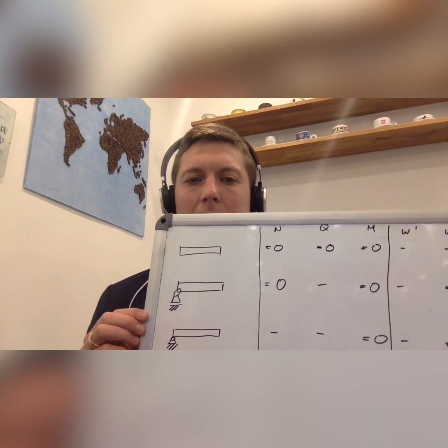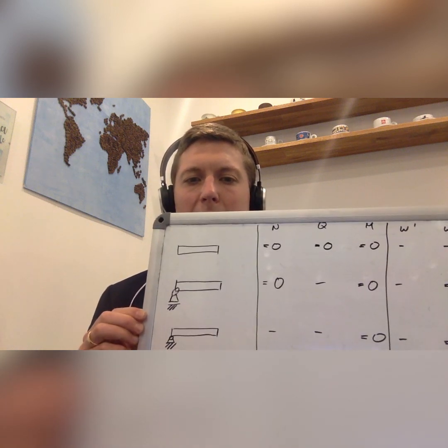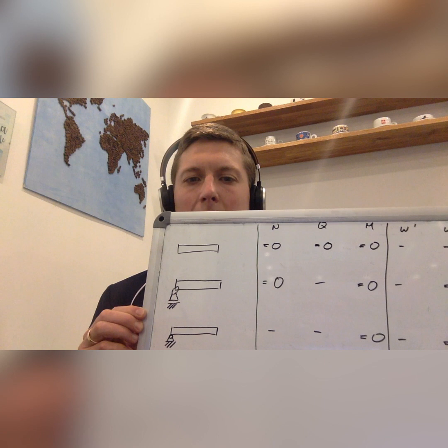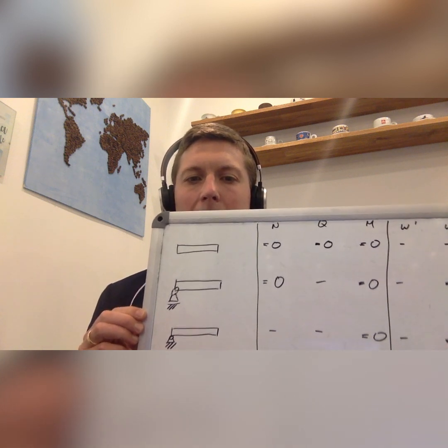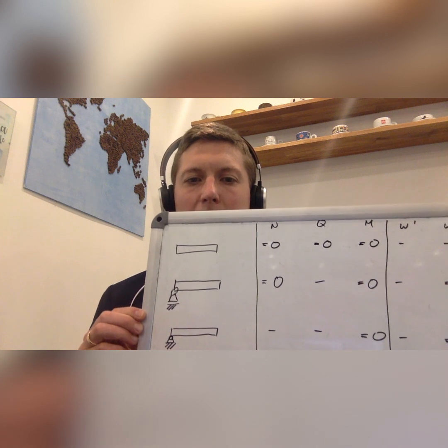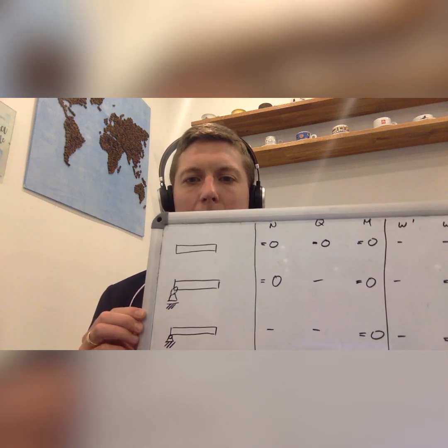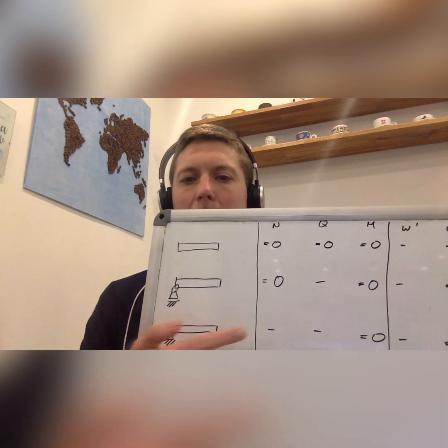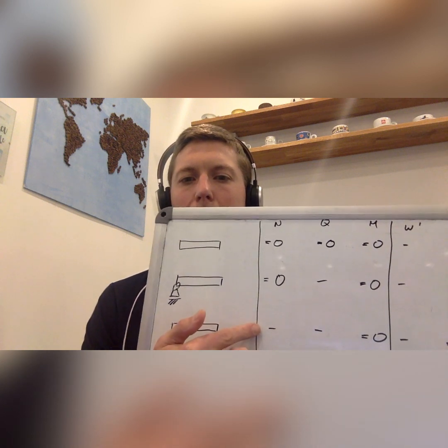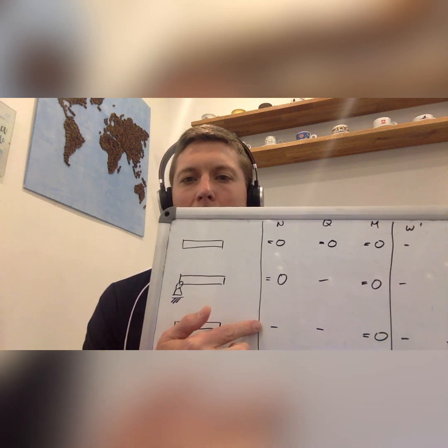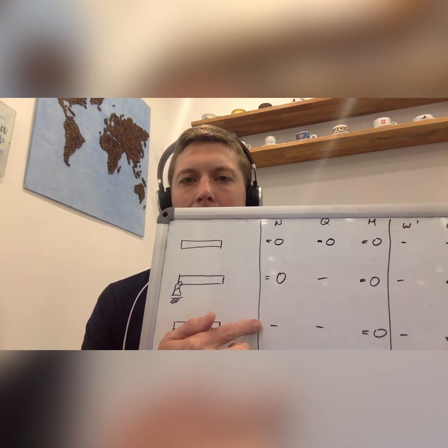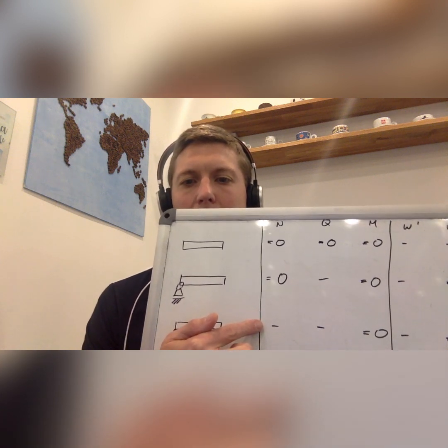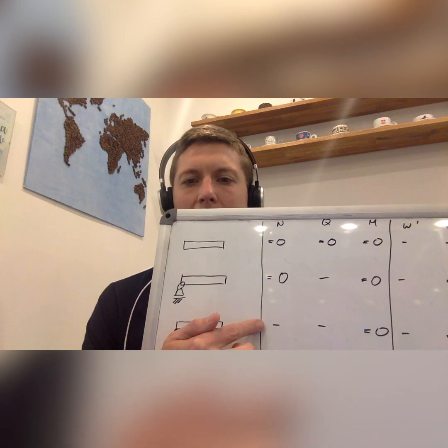So there is a horizontal force which prevents the movement to the left or to the right. And of course, this horizontal bearing force has to balance the normal force within the beam. So we cannot state a boundary condition for the normal forces. It could be an arbitrary value. So you could state that the normal force at the position x equals 0 equals minus the bearing force in horizontal direction, but you cannot state that it is 0.